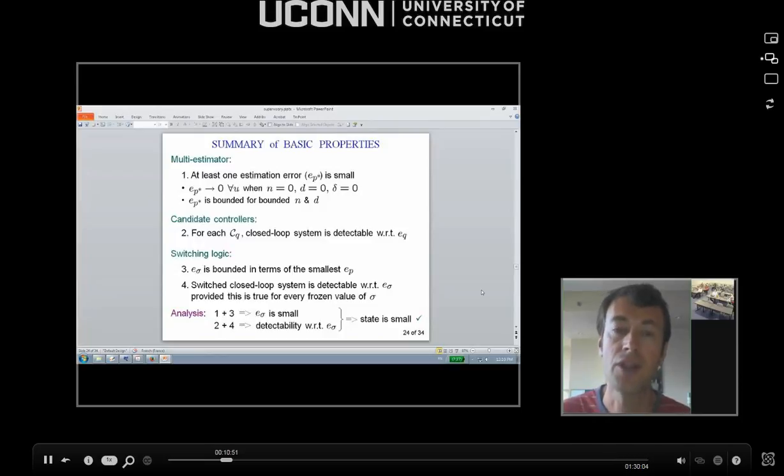For linear plants, there are general results available from the adaptive control literature, which say that the matched estimation error should be small in some sense, and small means convergence in the ideal case of no disturbances in model dynamics, and bounded, so gracefully degrading in the presence of noise and disturbances. We also have on this first property some results for special classes of nonlinear plants. Those of you who want more details, just contact me and I'll be happy to provide them. There are also references in the last chapter of my book on switched systems that address this point.